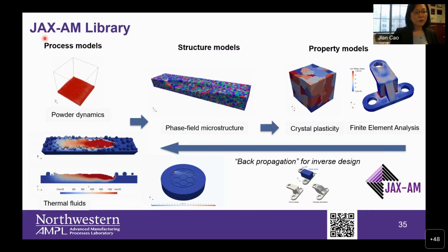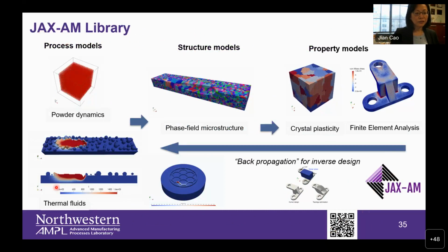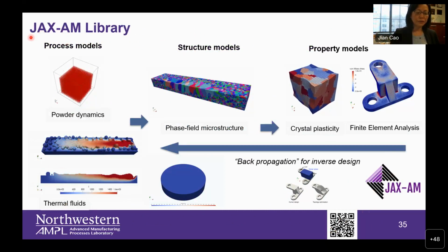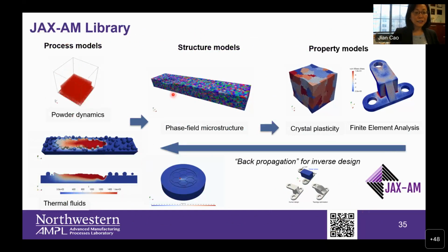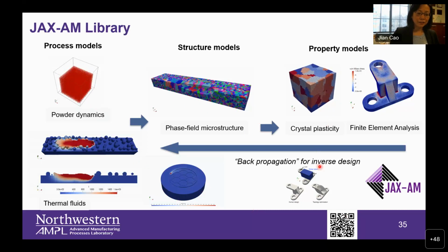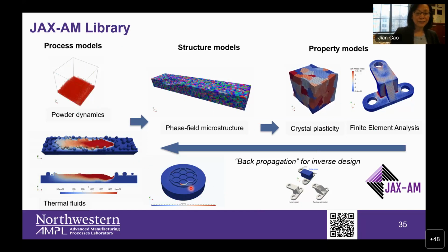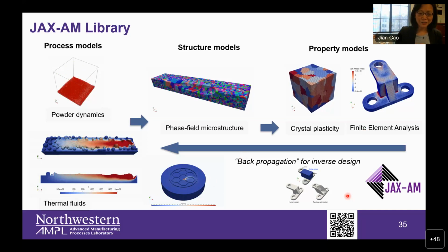The idea is, for JAX-AM, you can use it to simulate the thermal fluids using the JAX library, as I mentioned earlier. With the heat input, you can also simulate the local grain growth. With the grain growth, you can simulate the crystal plasticity. We also have an FEM version, which you can use to do topology optimization. Ultimately, once it's fully built up, you can have location-specific material properties coming from the additive process and do the whole co-design, as I mentioned earlier. This is a long-term goal, and we are getting closer and closer, which I think is very promising.